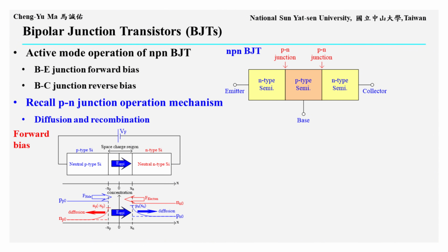Similarly, majority carrier electrons in the N-type semiconductor are injected into the P-type semiconductor, diffuse there, and recombine with majority carrier holes in the P-type region. The hole motion from the P-type side to the N-type side produces current toward the right. The electron flow is toward the left, but because electrons are negatively charged, its contribution to the conventional current is also toward the right. Therefore, a forward-biased PN junction produces a conduction current from the P-type side to the N-type side. To obtain a noticeable conduction current, the injected carrier concentration gradient must be large enough.